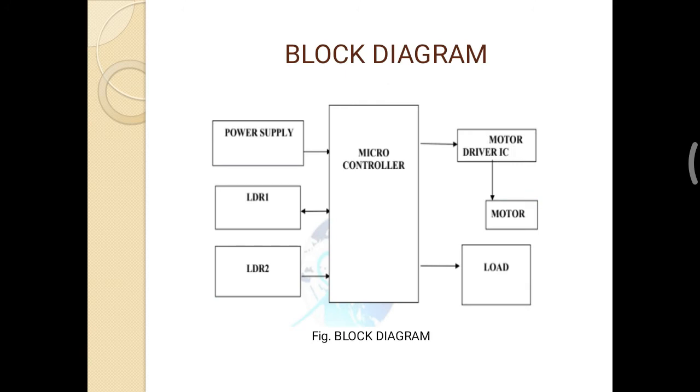Now let us see the block diagram of this. The power supply is given to the microcontroller, and the microcontroller is interfacing with the two LDRs. The microcontroller gives the signal to the motor driver IC, and the motor driver IC drives the motor, which is the load.